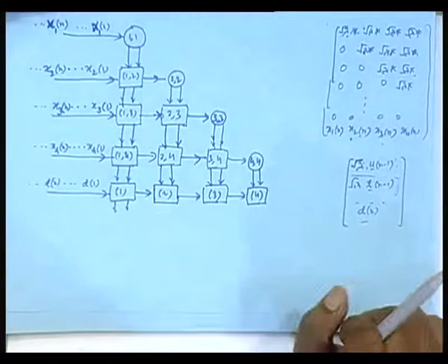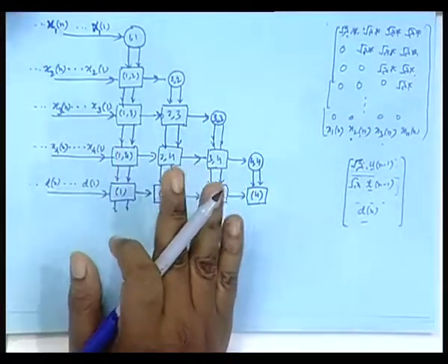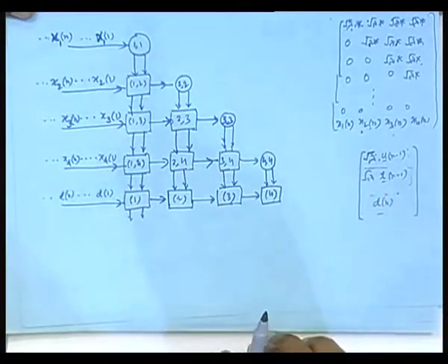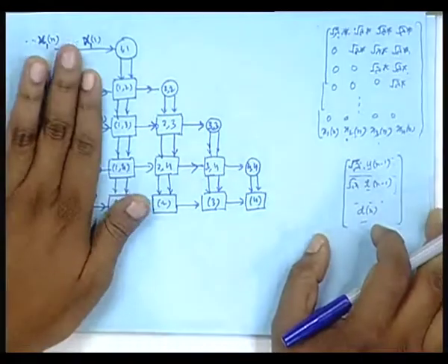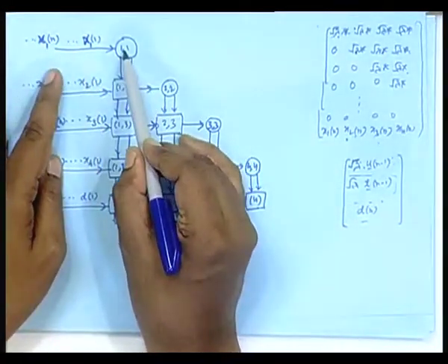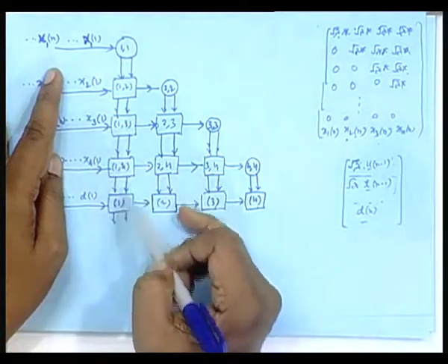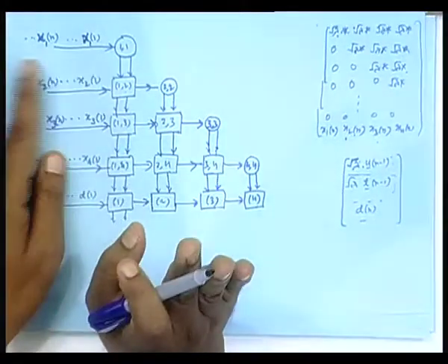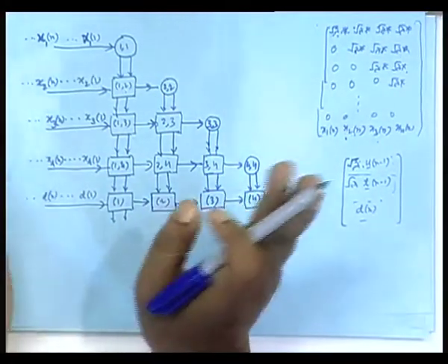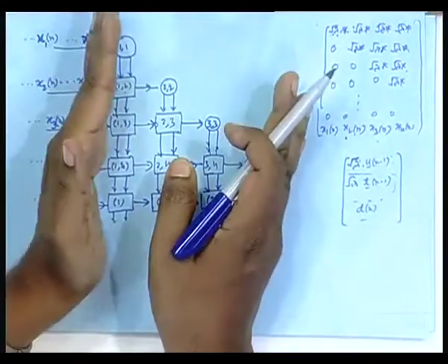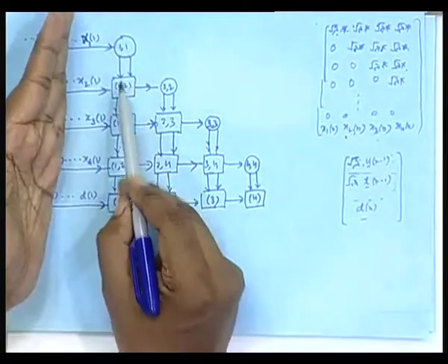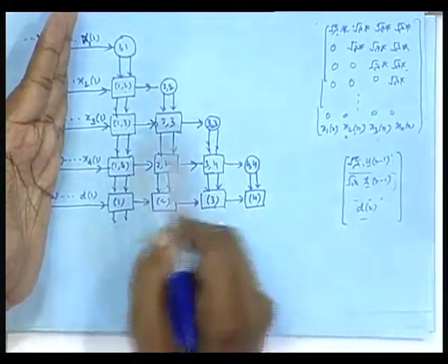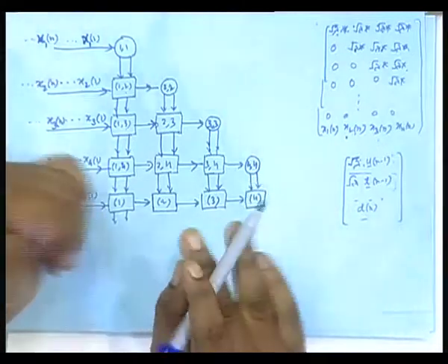But this is now just for triangularization of the matrix and corresponding rotation of the upper part of this vector. Now, here as such, this computation you have to do, followed by this, followed by this, followed by this, followed by this, these two. You see, if I have to do the entire computation, so much time will be taken. Before I allow the n+1th data vector to move in, I have to complete this, that result will be here, to complete this, both this, which then this, you can find out the total time required. That will be quite huge.